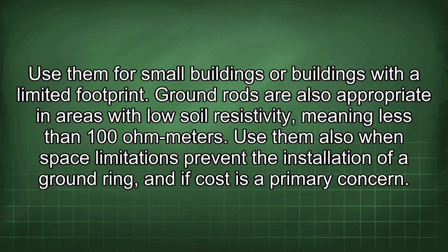Use them for small buildings or buildings with a limited footprint. Ground rods are also appropriate in areas with low soil resistivity, meaning less than 100 ohm meters. Use them also when space limitations prevent the installation of a ground ring and if cost is a primary concern.